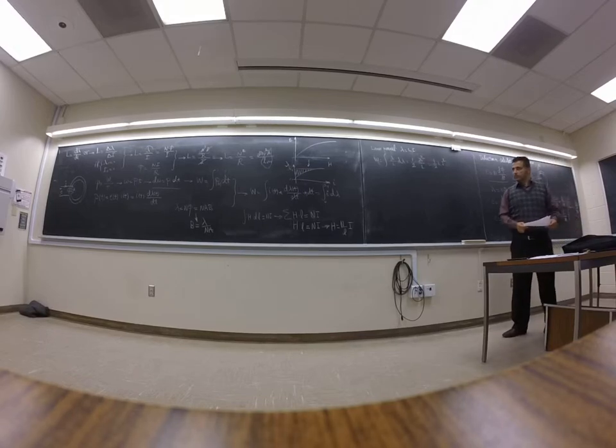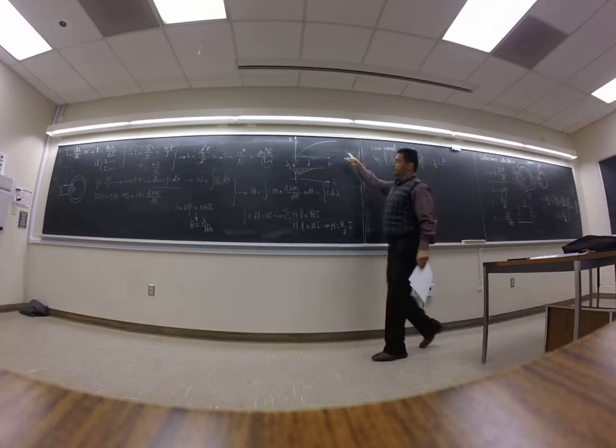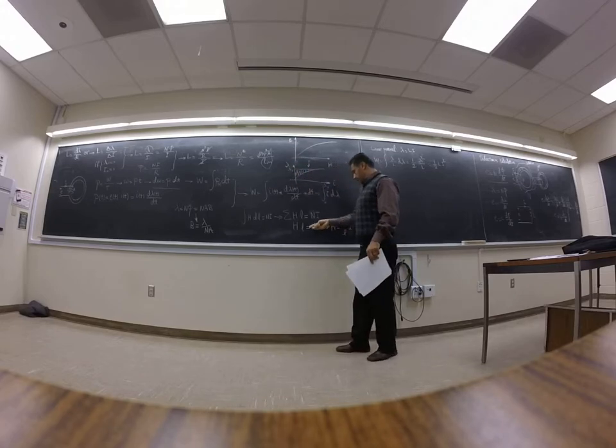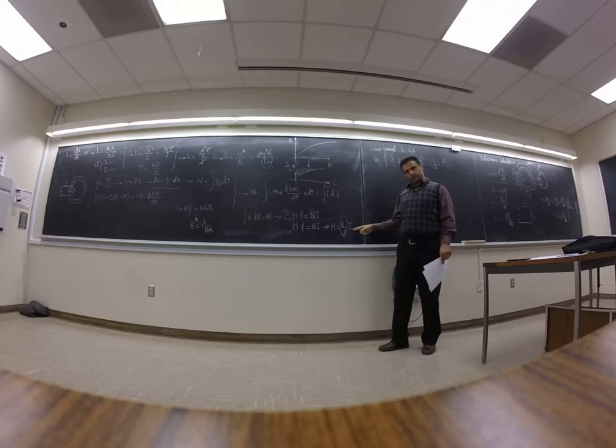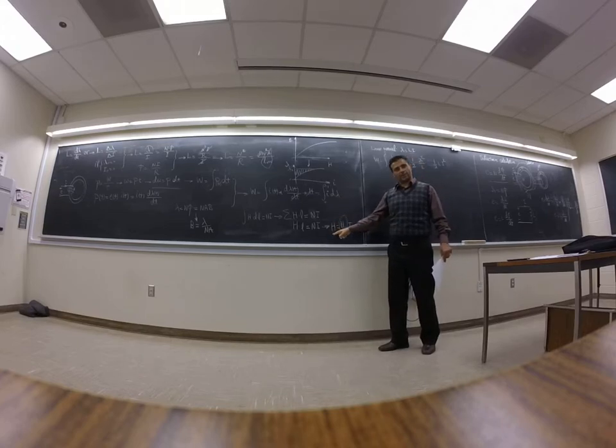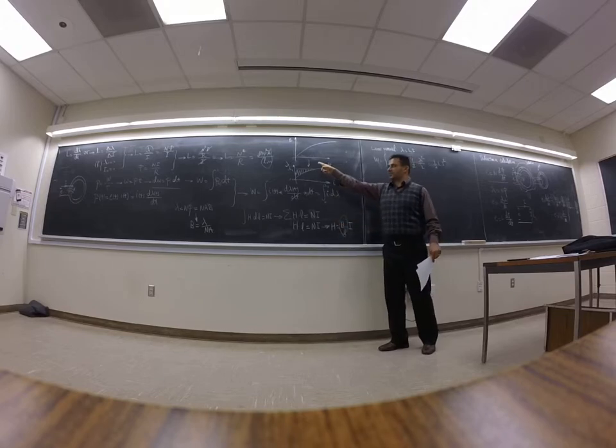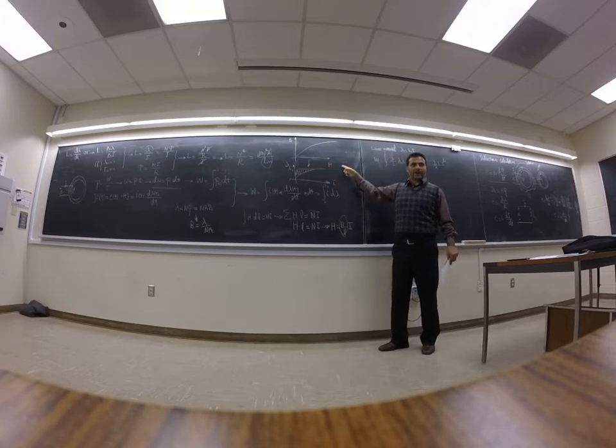How do you come up to this curve, I versus lambda? From this curve. I said H, you can convert it whatever I have. Actually, I should have put it the other way. I should say I is equal to L over N times H. You can multiply this axis by L over N. L is the length of the magnetic circuit, N is the number of turns.